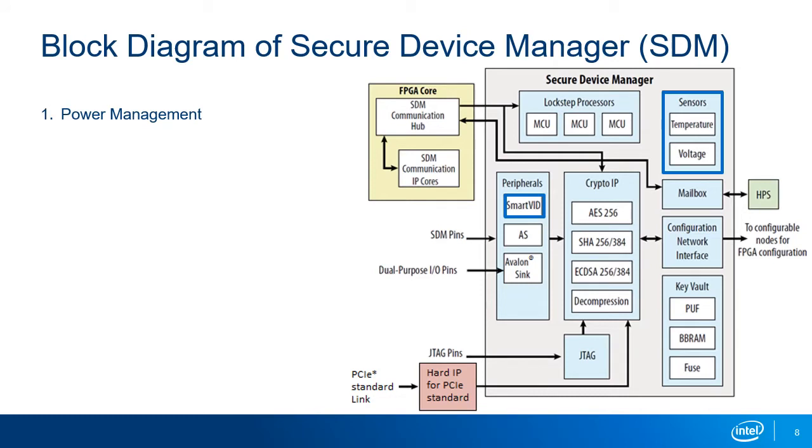The power management block consists of a voltage and temperature sensor which enables the Smart VID feature via an external PM-bus voltage regulator. Agilex also introduces the addition of the active low catastrophic trip signal, which is asserted low when the core temperature exceeds 125 degrees Celsius.